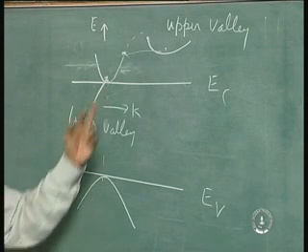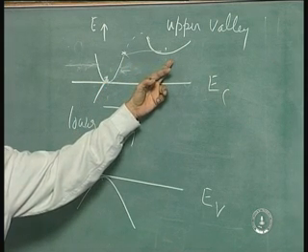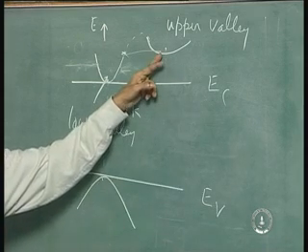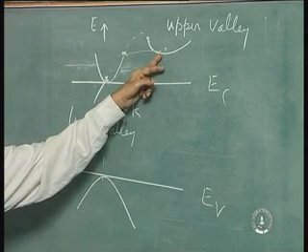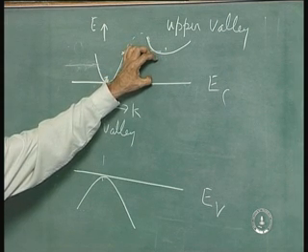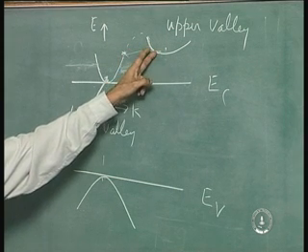Finally, if all these electrons have got transferred onto that, the effective velocity of those will be smaller. And the mobility here is almost closer to that of silicon, because the effective mass is closer to that of silicon. And once it is transferred here, if you increase the electric field further, it behaves like in silicon, the saturation velocity occurs here.